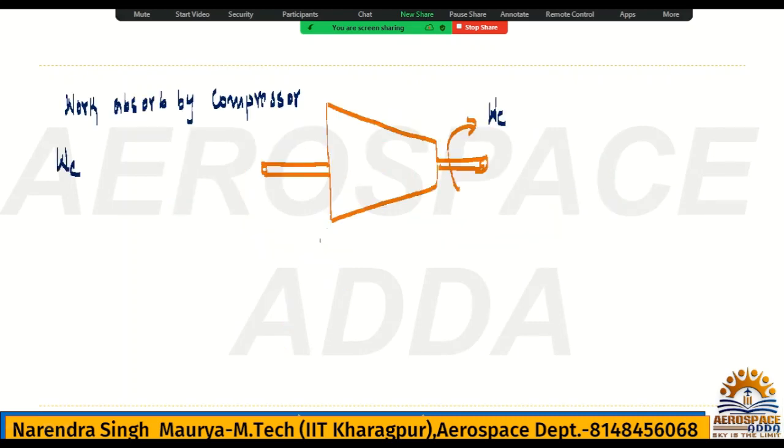Now check, this station, as I have told you, the inlet of the compressor will be 1. Inside the engine you always talk in total quantities, stagnation or total. So the total temperature at inlet will be T01, because this is station number 1 and this is station number 2. So what is the temperature here? It is T02. What is the pressure here? It is P01, and what is the pressure here? It is P02. All right, this is the way to write the numbering. It is a work consuming device, work absorbed by the compressor.